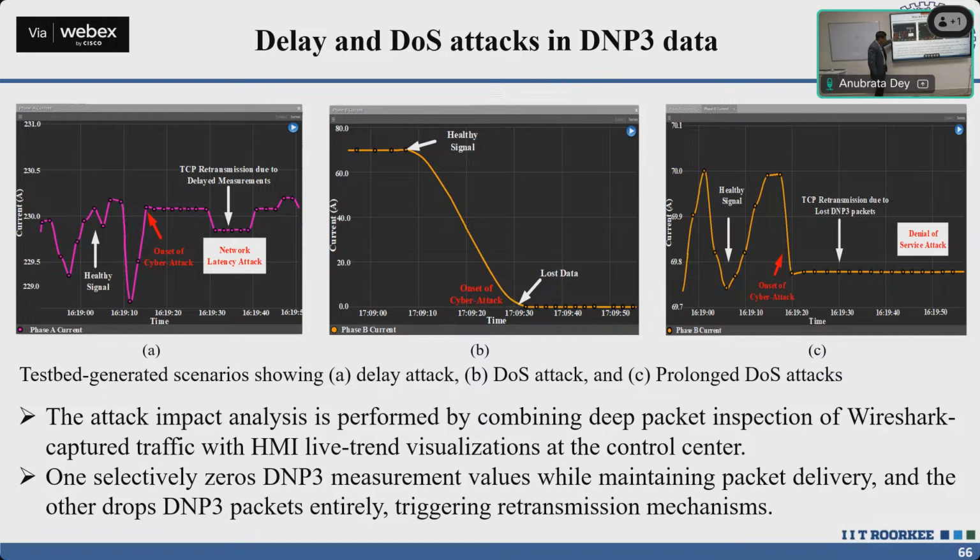In the first category, I have mentioned delay attack, DOS attack, and prolonged DOS attack. Here there is a delay; you can see somewhere some delay is created. When the PMU is transferring data to the PDC, you add some significant delay, using the DNP3 protocol. This is for the SCADA system.